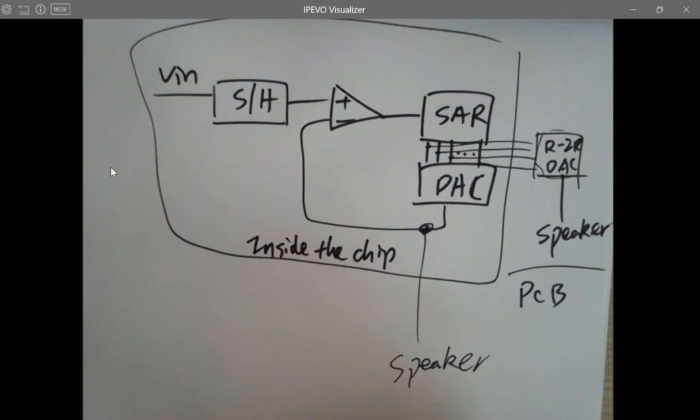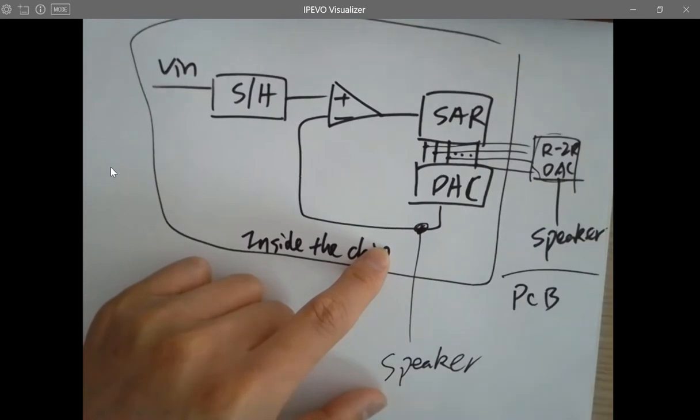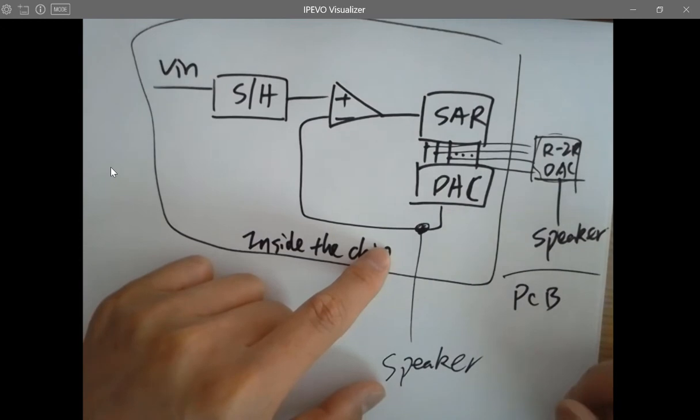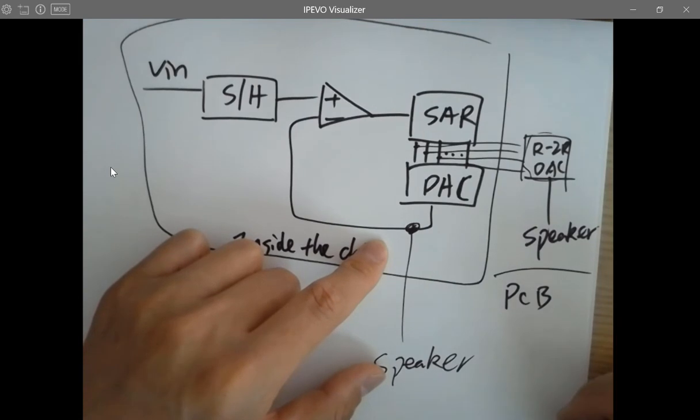Remember when you were drawing that state diagram, for the SAR ADC, how many states? If it's an 8-bit SAR ADC, how many states do you need to finish the converting cycle? No, n+1, right? 9, yeah. So you need 9 states to finish one conversion.